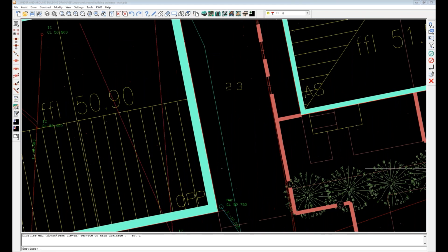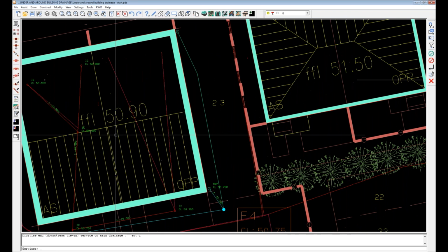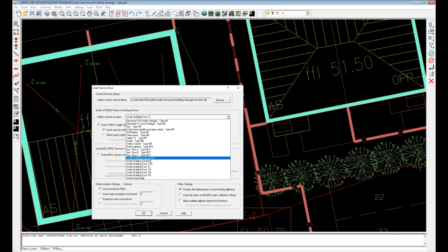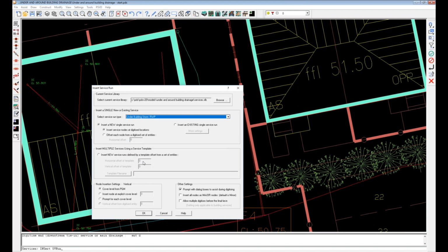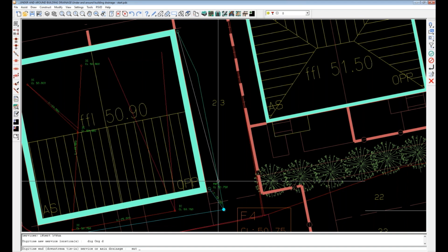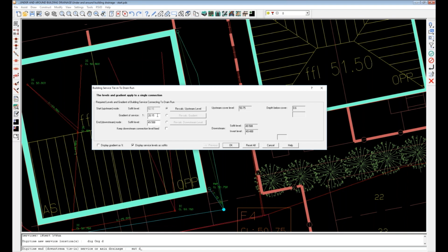Okay. And then one final thing I just want to show you is this. Particularly when we're doing underbuilding drainage, people started talking about, oh, well, we've got piled foundations or pile caps. We've got things that we've got to bend our pipes around. Whilst you could put this in as the bend point as a node, it wouldn't really be a bend. It would just be a sort of kink, effectively, which you don't really want. And so we have introduced the concept of a bend, which I'll show you in a minute.